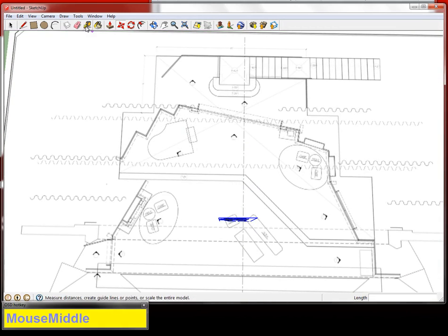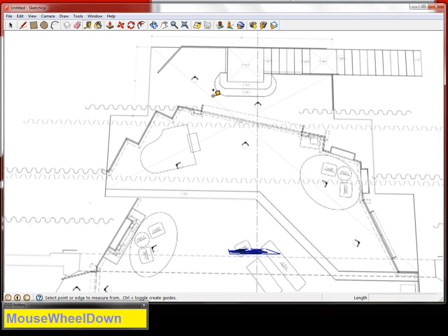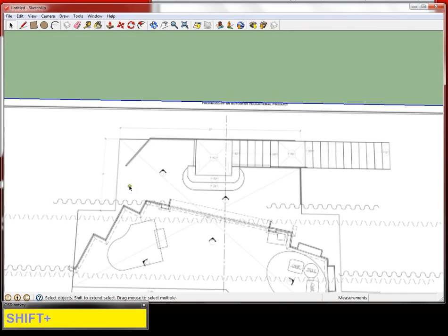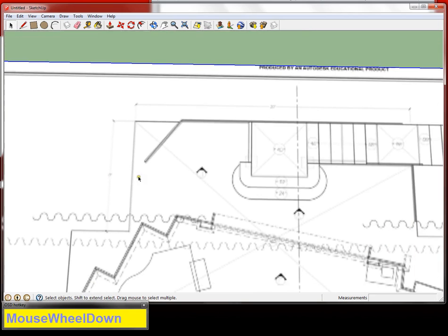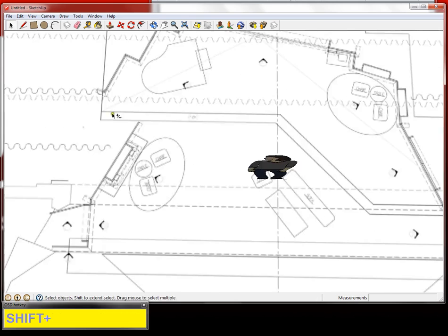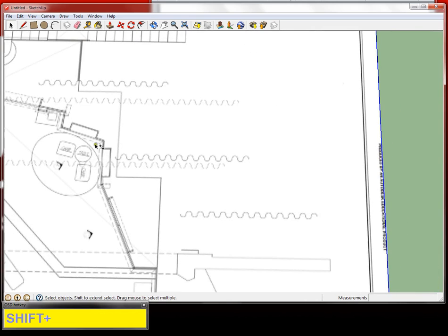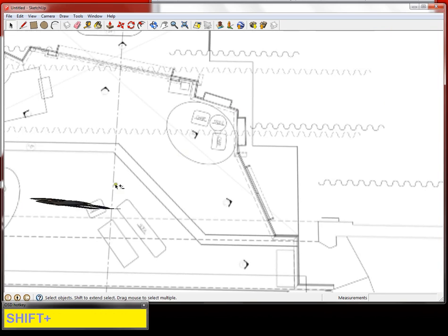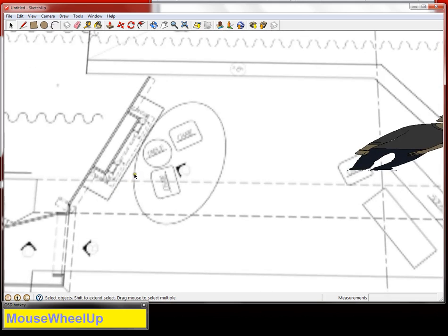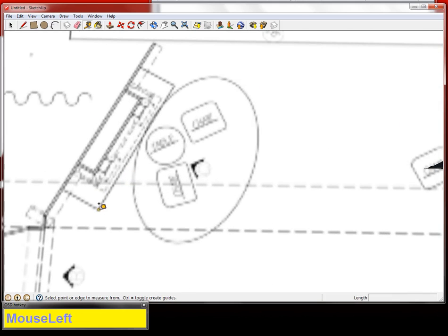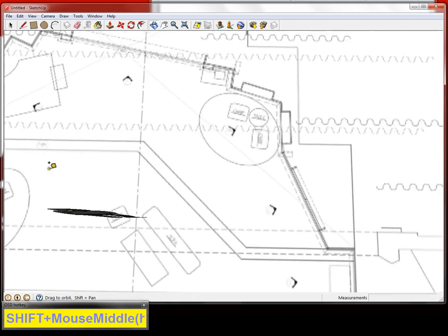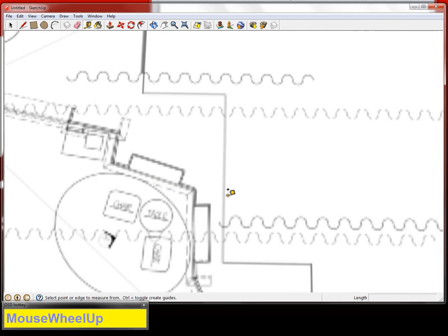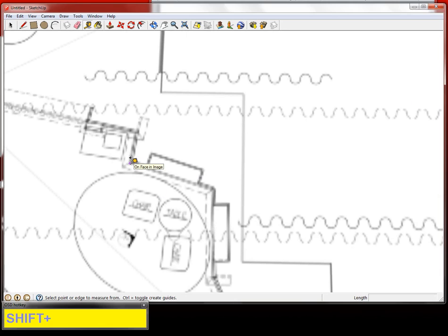Well, we use the tape measure tool. I'm going to grab the tape measure tool and zoom in to something that I know the size of. I have lots of choices here, because I can read that this is 8 feet or 20 feet, or I can use something I know the size of, like this bookshelf, which I know is 4 feet, and a 4 foot flat because we've already made it, or this fireplace. For instance, I know that this fireplace is 5 foot 8 inches. Actually, I'm not so sure about that anymore. So I know that this one's 4 feet. Let's go with that.